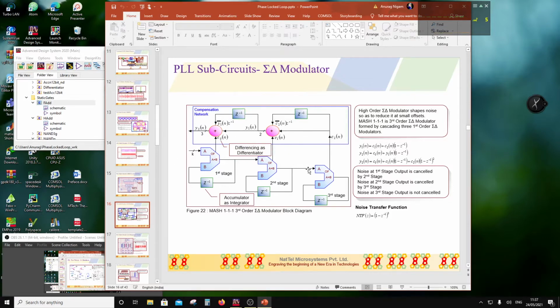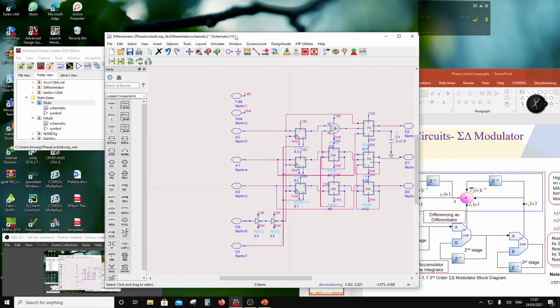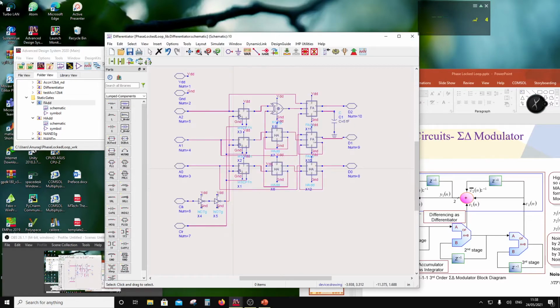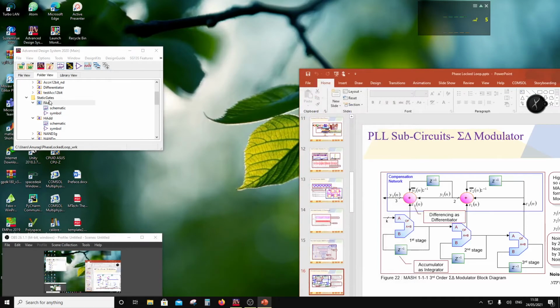So let's do the remaining part, right? This is called the difference circuit. So I'm just going to make sure this difference circuit is okay before proceeding further. So what did I do? I took D flip-flops with the bar, so that's going to do one's complement, and then I did a half adder with 001 addition, so that gave me 2's complement, and then the 2's complement I added with the delayed copy of A0, A1, A2, so I did a delayed copy sum with A0, A1, A2 to give D0, D1, D2, so that is equivalent to this Z minus and then this C2 bar summed with C1n, right? So that's that. Okay, so having done that, I am going to make a symbol for this one, right?